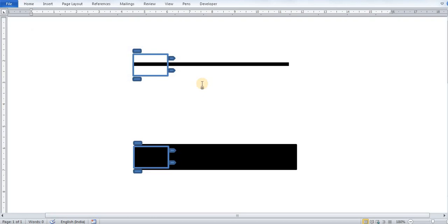Why? Because the number of actions and number of sensors, they have a relation. It is 2 raised to n equal to number of actions, where n is the number of sensors. Because we are using digital sensors, we use base 2. So 2 raised to n, where n is the number of sensors, will give you the total number of actions you can program using those n sensors. So in this case, we need 2 sensors because we want 4 actions. 2 raised to 2 is 4. So we need 2 sensors.